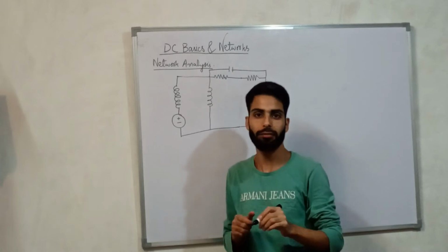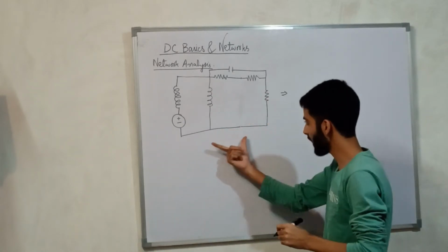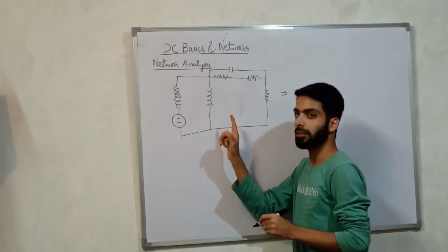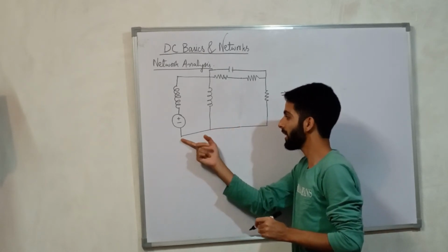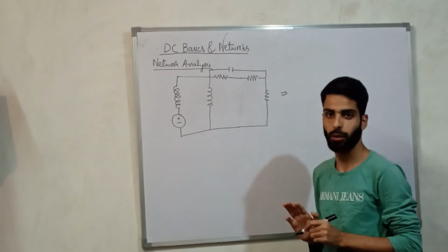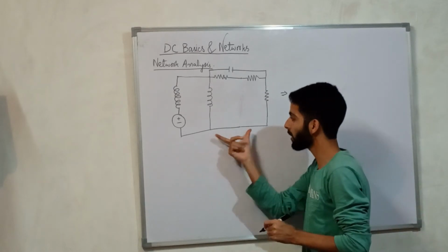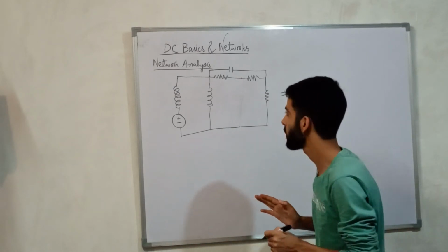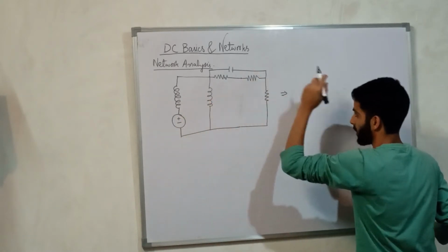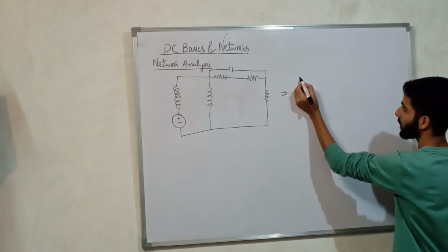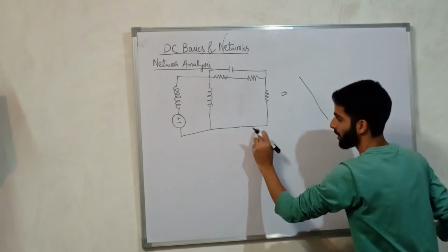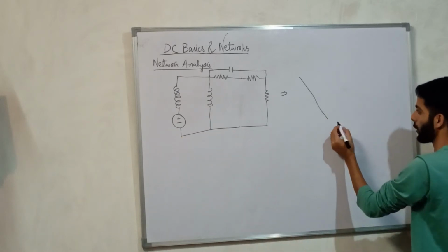One important thing that we have to note here is that the voltage, that is the potential level, located here on the bottom branch is the same for those 1, 2 and 3 points. So we can tie up all those 3 points into a single common point. Okay, let us do this. Eradicating those parameters, it will be something like this. We will combine all the 3 points on the bottom into a single point.